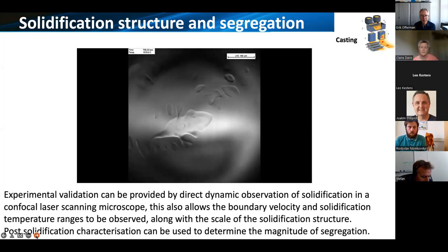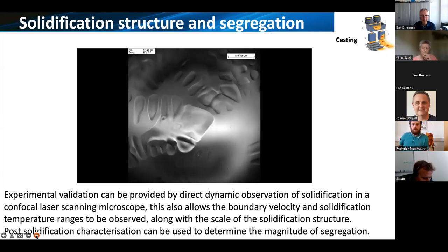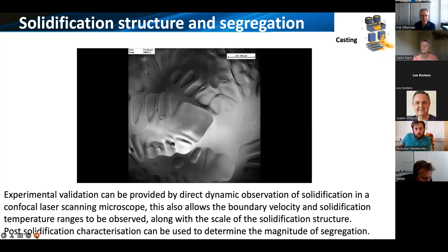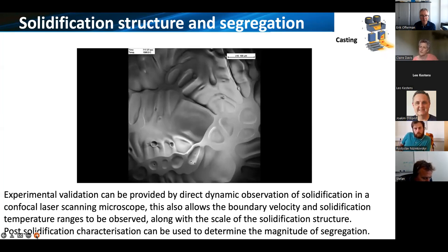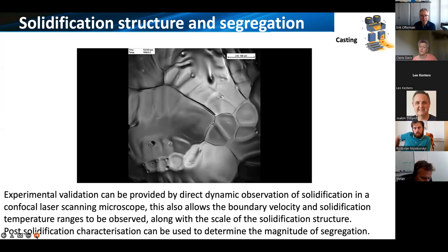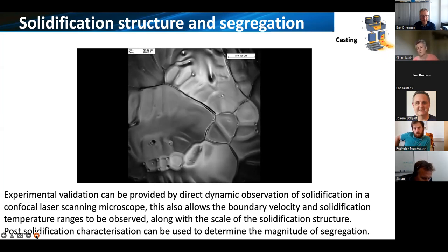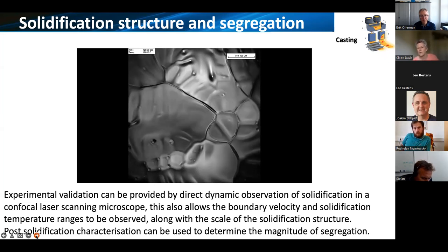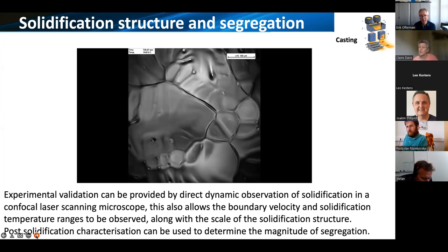And the thing you might have noticed just at the end of the video, before it looped back, is at the end of solidification, we get then the transformation to the austenite, and actually you can see the austenite grain boundaries. And should we continue with this, you can see the austenite grain growth, and that's the thermal etching effect. So just here, we can see some of those boundaries.